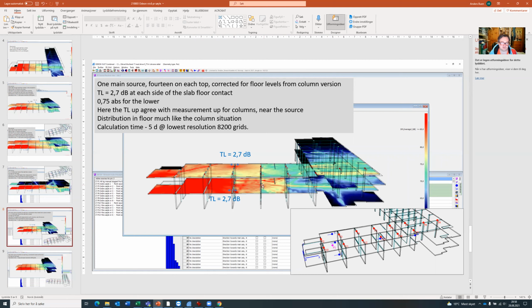I know what the answer is, at least for the same floor. And it's quite easy to test when there are not many people in the building, and also the transmission loss from the floor below to the floor above is quite simple to measure. But you need to know the instrumentation. I use an accelerometer, but you can do it also with a sound level meter if you can have a closed room for those.